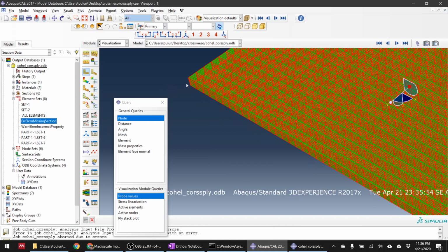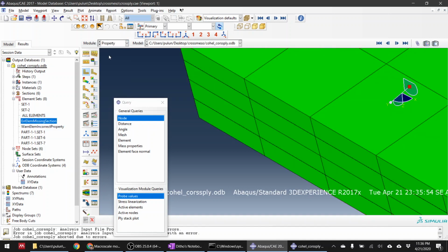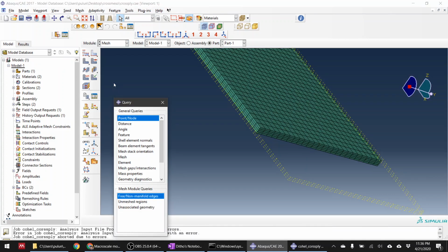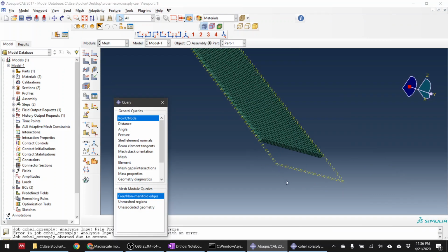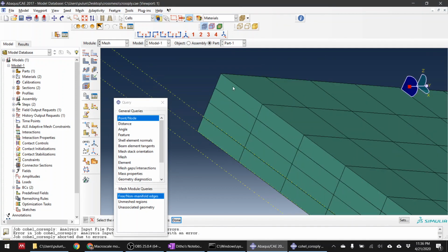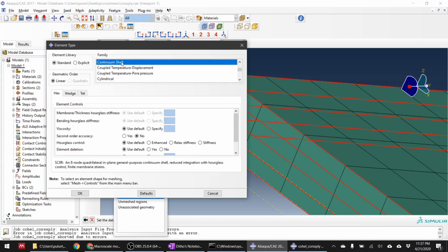Error, missing section. It seems that there's a missing section with incorrect properties. Oh no. Yes. We were using 3D solid for this one. No, no, we should not. So here, before, I chose this one, this one, this one, this one, clicked done, and then I used 3D stress like this. Okay, this is wrong. You want to use continuum shell. Okay, this is shell formulation.